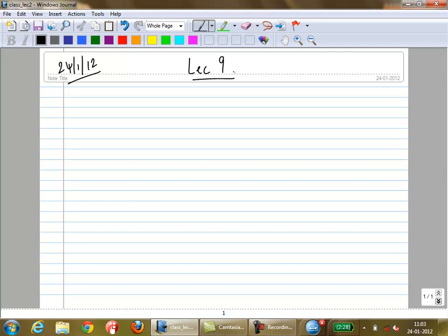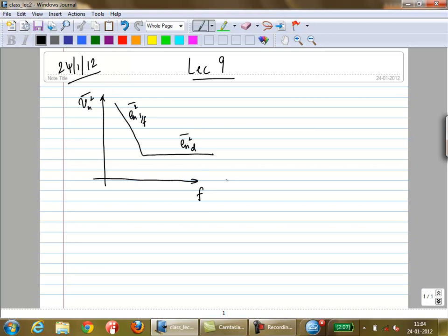But before that, I just wanted to point out one thing about flicker noise. Let us take a look at what happens when you look at integrated flicker noise. If you take a MOSFET, you have 1 over F noise at very low frequencies, flicker noise. Suppose you're going to integrate this 1 over F noise to find the overall noise in a particular frequency band.